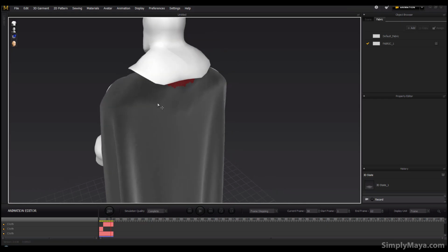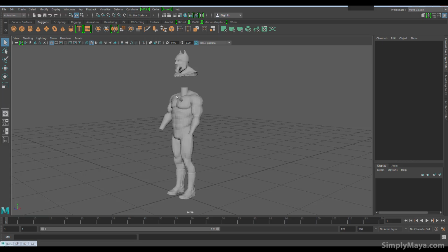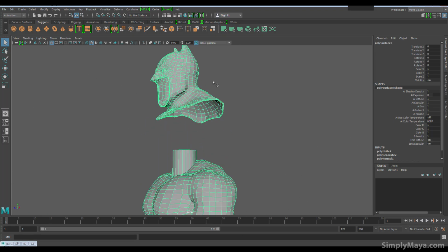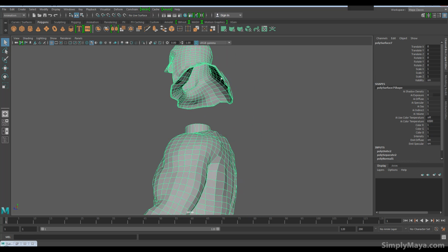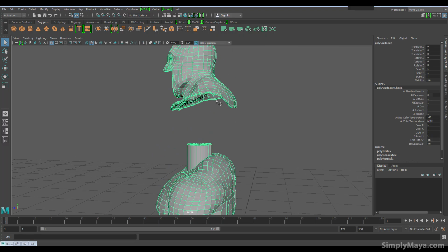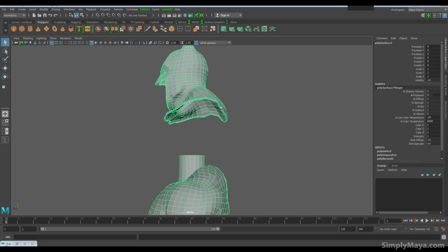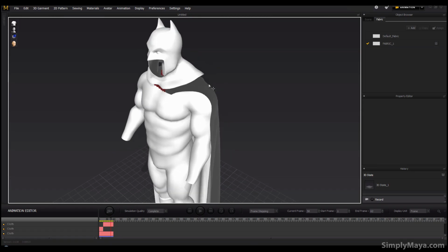Okay, so as you can see, well, we've got that pinning in place. There's less chance of bisection happening. Another thing that we could have done is we probably lowered the head down too quickly. So the bisection is happening because we haven't got enough frames on here. So if we'd given this 300 frames to lower that head down and let it settle really slowly, that could have helped. It also could have helped if we had a closed model here, which you can obviously, with all the stuff Jay's taught you, fill the bottom of this up, or certainly just extrude it inwards a bit so it's got a bit more heft, a bit more clout to it when it clamps on the material to clamp it down. Because this edge here is a little thin for that particular process. But regardless, this is enough to get this next bit done.